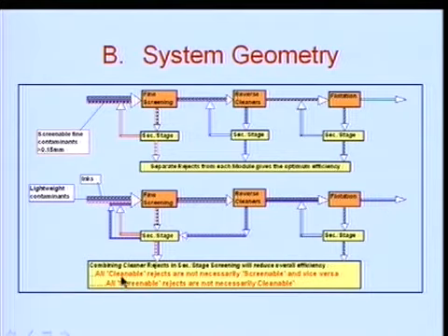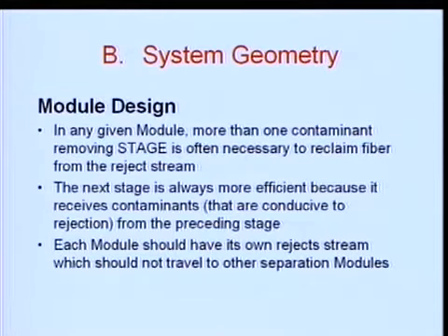So, ultimately all cleanable rejects are not necessarily screenable, and again the other way, all screenable rejects are not necessarily cleanable. That is a fundamental thing, and you have to remember that. If anybody says, oh, what you can do in cleaners, you do not need cleaners, I can do it in screens, that can never be true.